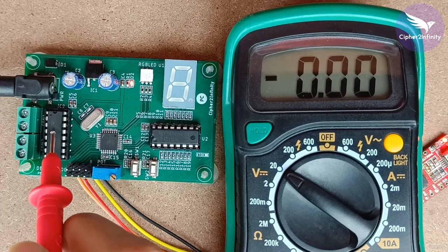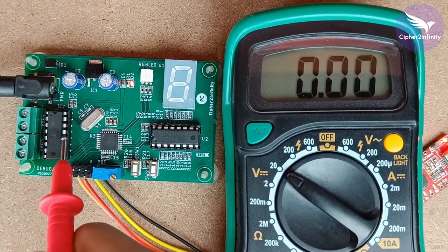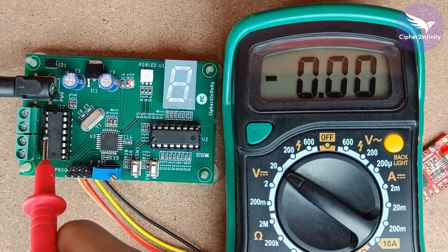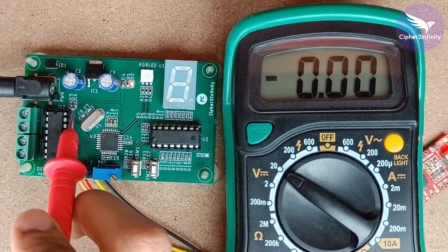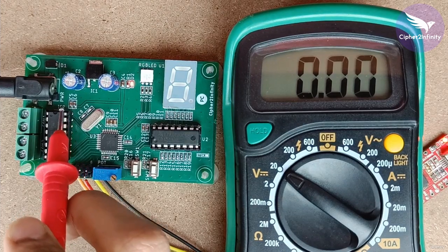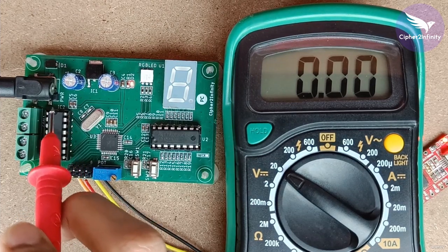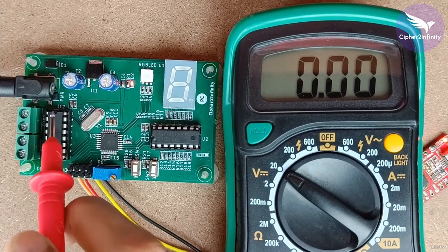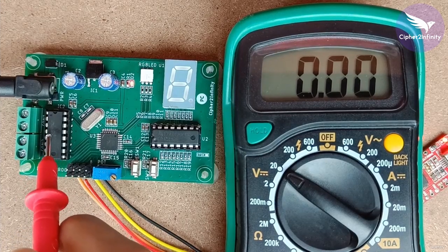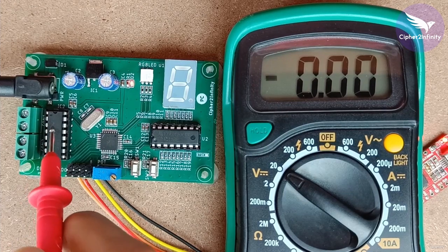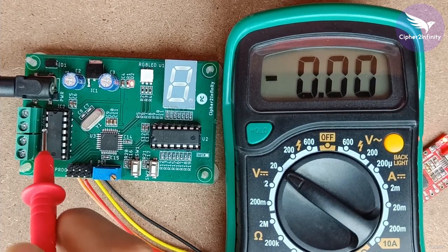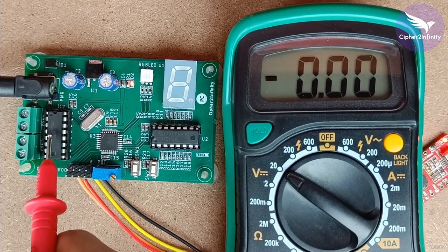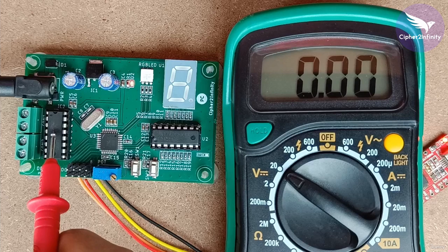The first mistake that you can make is related to the IC base. When you solder the IC base on the PCB, you have to make sure that the polarity of the IC base is proper. You have to match the notch of the IC base with the notch which is present on the silkscreen. In the same way, you have to check the polarity of the IC when you place the IC or when you press the IC on the IC base. That's the first mistake that you should avoid when you deal with the L293D section.